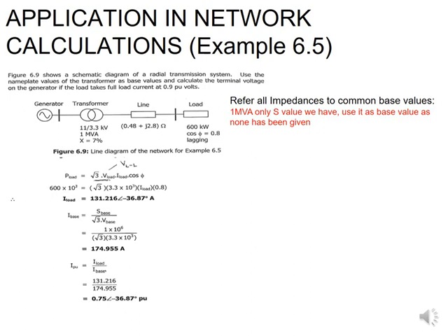Then I must now utilize what I have been given in order to work out the impedances of all my different systems. So I start with the transformer because I can't start with the generator. I don't have any information there. So on my transformer, because I'm utilizing that transformer as my base values, it means that my S base and my S nameplate are the same. So therefore that 7% becomes my Z per unit.